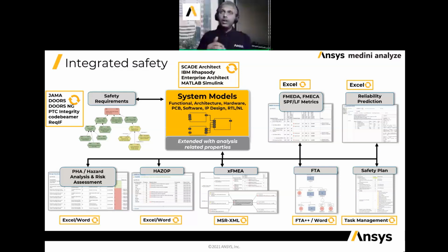And something that's also equally important is the reliability prediction of electronic components. For each of the electronic components, we know that they suffer from random failures. Now, there is a particular failure rate that we can predict or estimate given a component, the quality of the component, and the usage environment of the component, maybe the stress levels and so on as applied. So there are multiple failure rate catalogs, or handbooks as they are called, that are built into this particular solution, using which you will be able to estimate or predict the failure rate of individual components. It could be resistor, capacitor, integrated circuits, or many other components from the electronics domain.